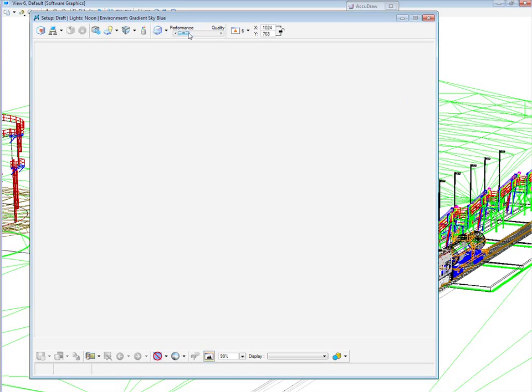You can see, obviously, we have a slider bar here of performance to quality, and you can adjust this however you wish. Personally, if you're going to select one of these settings here, I'd let Luxology set the performance quality standards for you. Okay, next icon on is which view you're going to be rendering from. And up in the little corner here it says view 6, so we're okay. But you can choose any of the other views of MicroStation, all 8 of them.